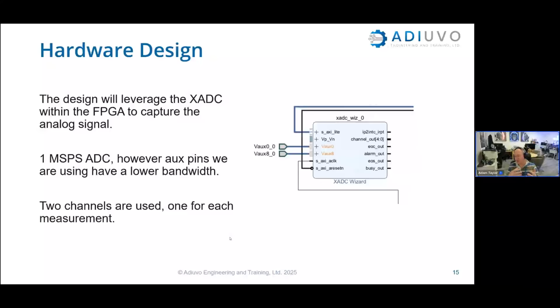But for us, we're measuring pretty much DC. We're going to set the DAC to one value. We're going to let it settle. We're going to take the measurements. We're going to flip that over, let it settle, take the measurements, calculate the output, and then move on. So it makes it nice and simple. Now, a little bit of an iteration to this circuit would be to use a switch that means that the same ADC is used for both measurements as well. So we are getting as close an input path as possible.